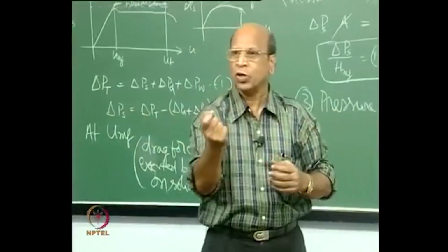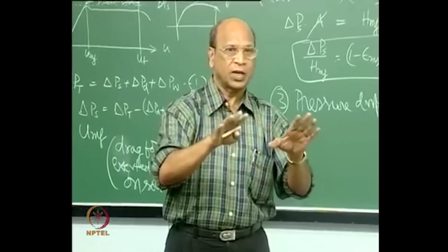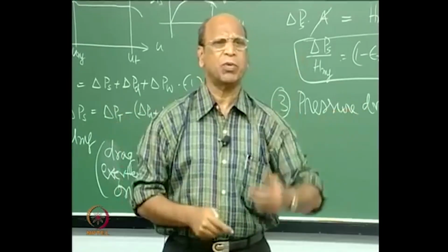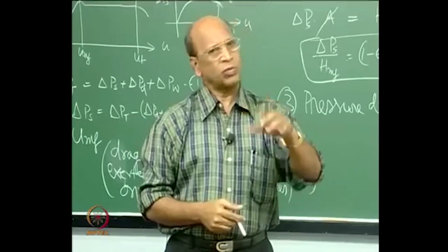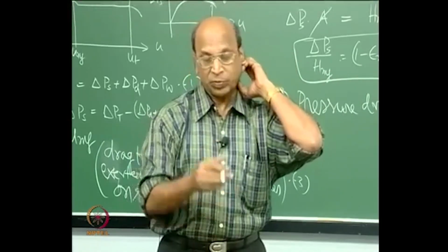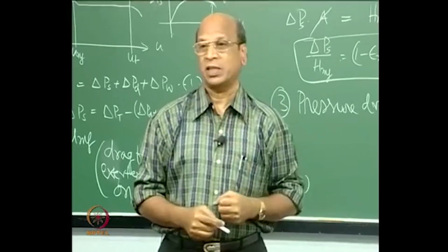We are not talking about each and every point, what is the interstitial velocity. We are not talking. Why? Because we cannot measure that very accurately. Same thing even with packed bed. In packed beds we use, whether a distillation column or any other use for packed beds, when you are using packed beds for a certain process, we never use interstitial velocity.